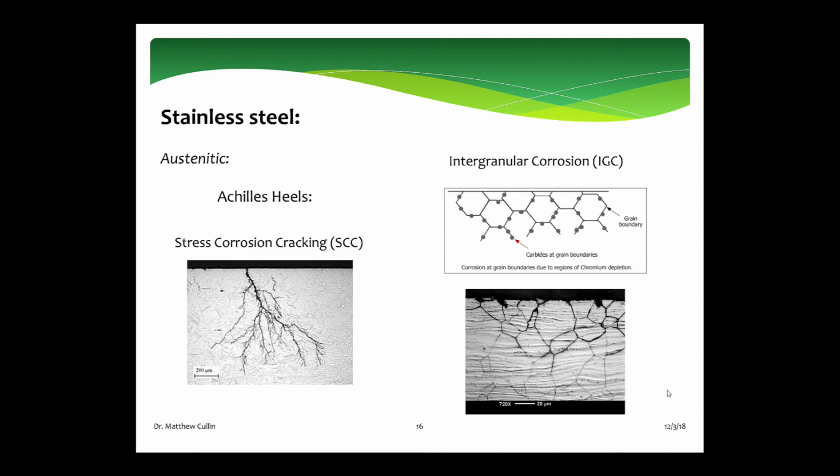Remember that with stress corrosion cracking, we have a static tensile load. So in this case, we would be pulling this way and that way, right? And we expose it to an environment that may or may not have chlorides, but if it does have chlorides, the stress corrosion cracking is going to be a bigger problem. No cyclic load, static load, and yet it cracks and it fails.